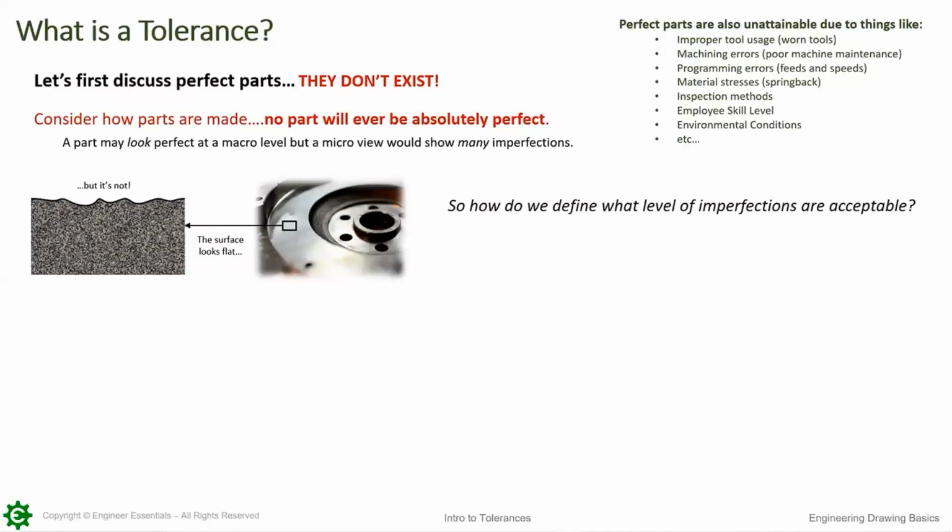For example, holding your phone in your hand, you can see that it has a width, a height, and a thickness. But how wide is too wide for them to have a repeatable process on their phone? Or too tall, or too thick? What is the tolerance on those dimensions that would be acceptable, that if they produce that part at the end of the day, they can accept it? Well, we dictate how much we can accept with tolerances.